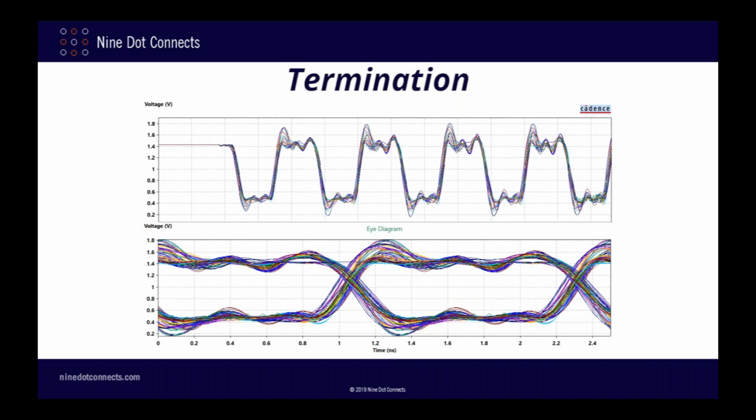Here I'm showing both the signal waveforms and the eye diagram. As you see, the signals are still a bit noisy and not quite as clean as for the data bus, but still plenty of eye opening is available. I would feel quite good about this design, and since I already know it works, my feelings are justified.